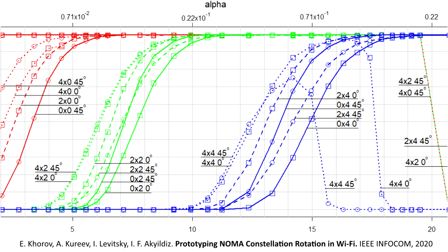There is also a difference of behavior for secondary QPSK and 16 QAM. Rotate when primary is BPSK and don't otherwise. The performance difference of secondary 16 QAM superposed with primary BPSK has already been shown in the demo. The superposition with primary 16 QAM shows a good performance, but the exact reasons for that are our future research.